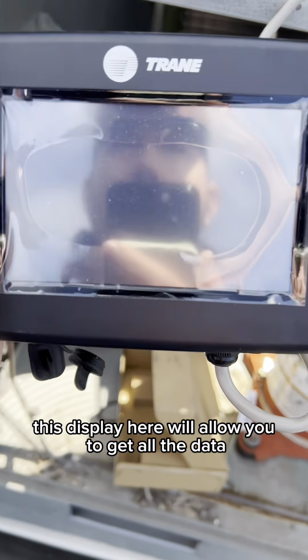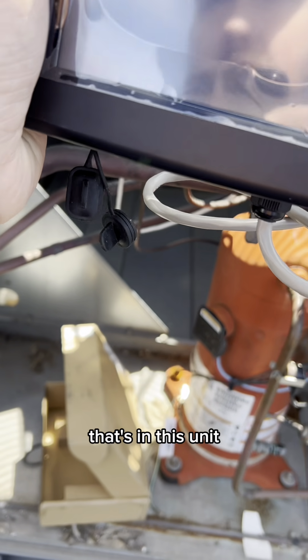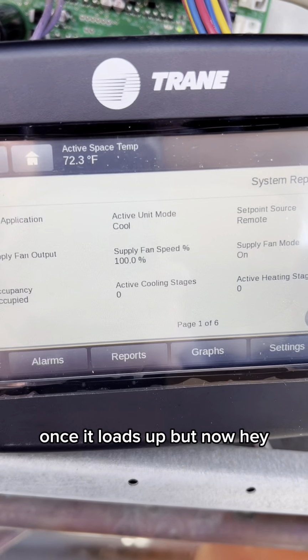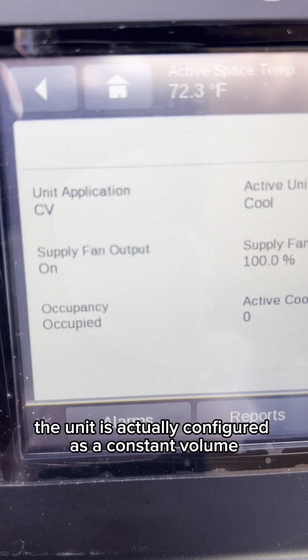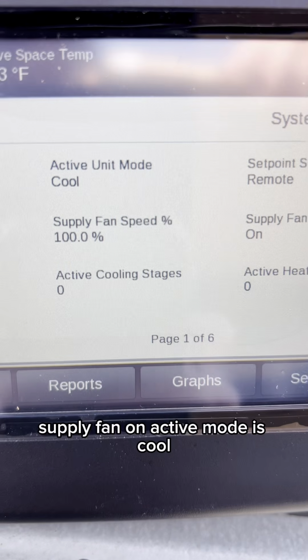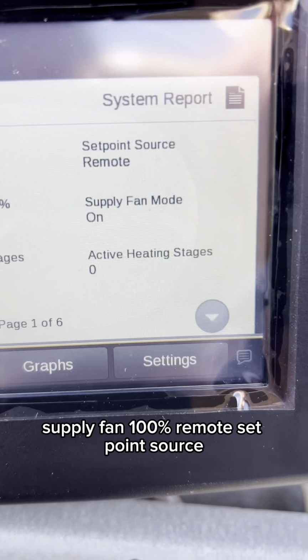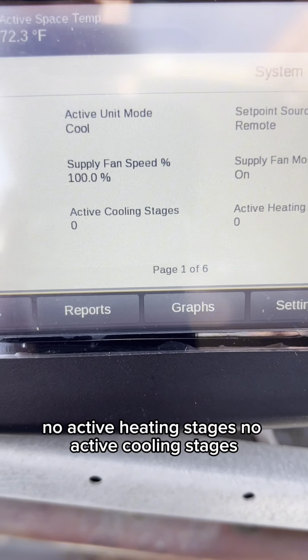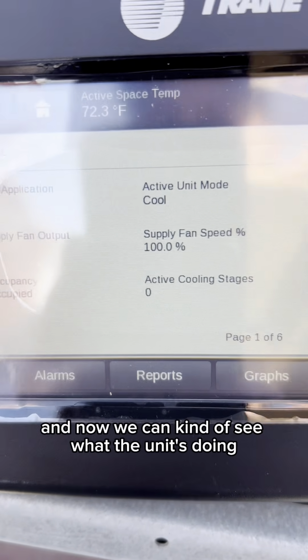This display here will allow you to get all the data that's in this unit and be able to see what it's actually doing once it loads up. But now, hey, we can see the unit is configured as constant volume. Supply fan on, active mode is cool, supply fan 100%, remote set point source because it is part of a BMS, no active heating stages, no active cooling stages, and now we can kind of see what the unit's doing.